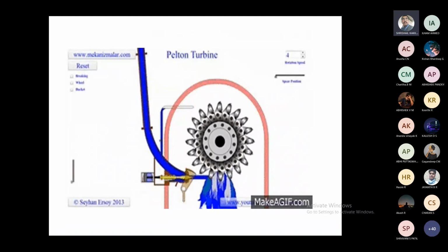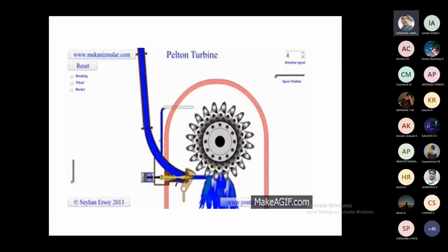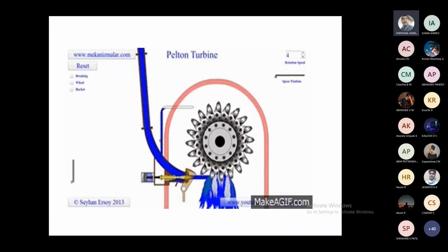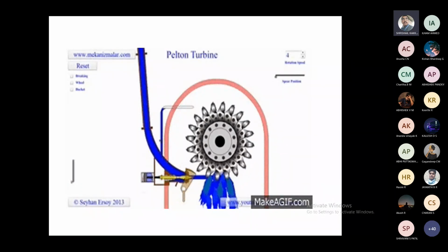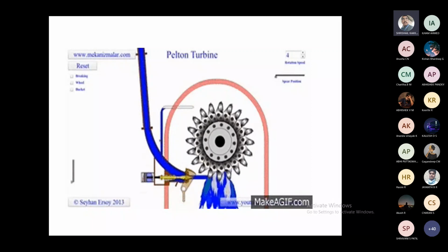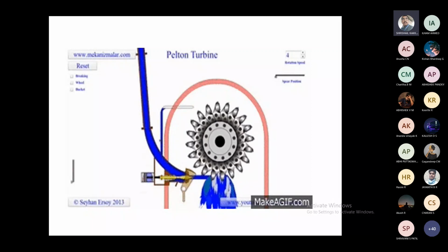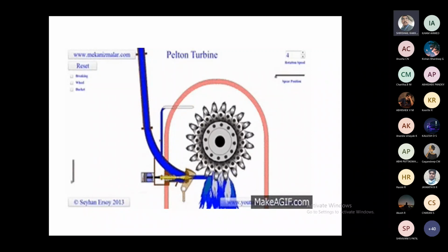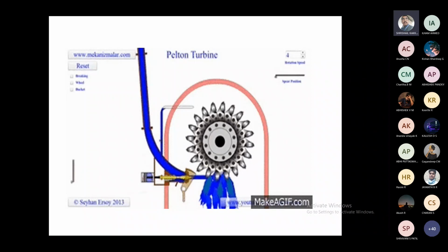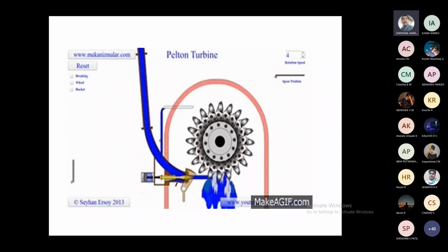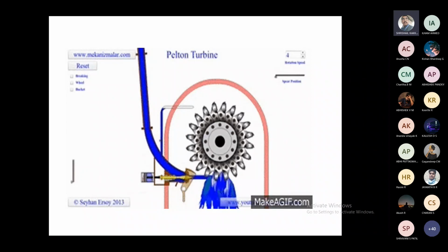When it is flowing through the penstock, it will be having high pressure and low velocity. When it is passing over the nozzle, the velocity will increase and the pressure will drop down to the atmosphere. At this high velocity, the resultant force acting on these vanes by means of a jet of water will cause the vanes to rotate.